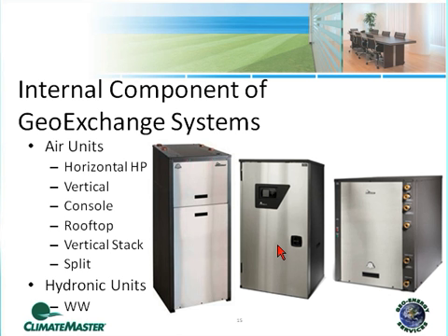This is kind of a specialized unit. One of the limitations that water-to-water units have on the hot water heating side is they're limited to about 120-degree hot water. So going back to the conventional systems here, the big water-to-water units, one of the things you typically have to do on your heating coils, instead of typically designing a 2-row heating coil, to maintain the same discharge air temperature with lower water temperatures of 120 degrees rather than a boiler temperature, say, of 160 to 180, you're going to need probably a 4-row or a 6-row heating coil instead